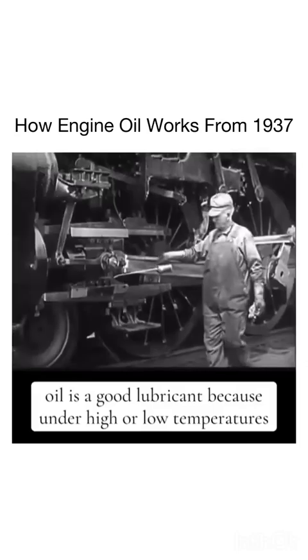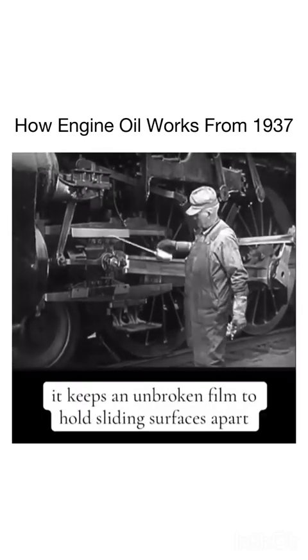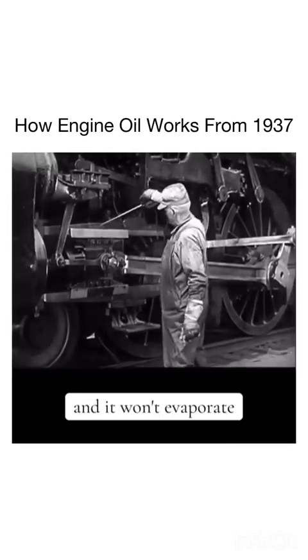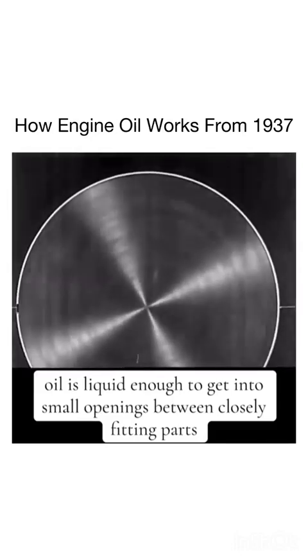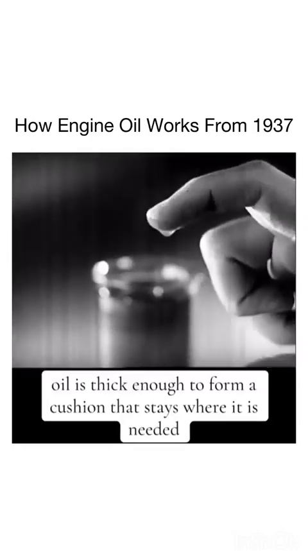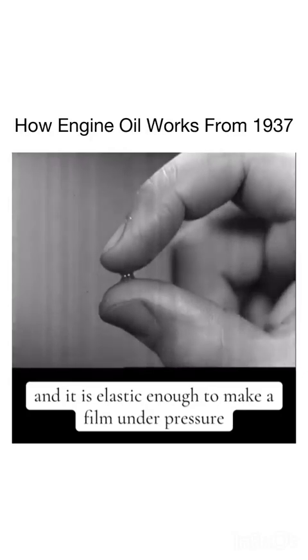Oil is a good lubricant because under high or low temperatures, it keeps an unbroken film to hold sliding surfaces apart, and it won't evaporate. Oil is liquid enough to get into small openings between closely fitting parts. Oil is thick enough to form a cushion that stays where it is needed, and it is elastic enough to make a film under pressure.